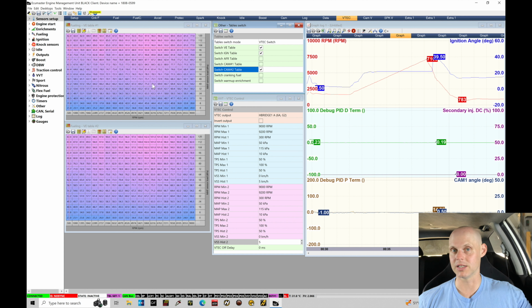And that's exactly why Honda does the calibration within the factory ECU. They have a table for low cam, a table for high cam, and in fact they actually have fuel and spark timing tables for every 10 degrees of variable cam movement. So there's a total of something like 16 or 20 tables for fuel and spark timing. It's very confusing. A lot of different tables to calibrate and tune. So this is a little bit more straightforward, but we want to follow along with that OEM programming logic at the very least for having a table 1, table 2, and doing that switching function between.